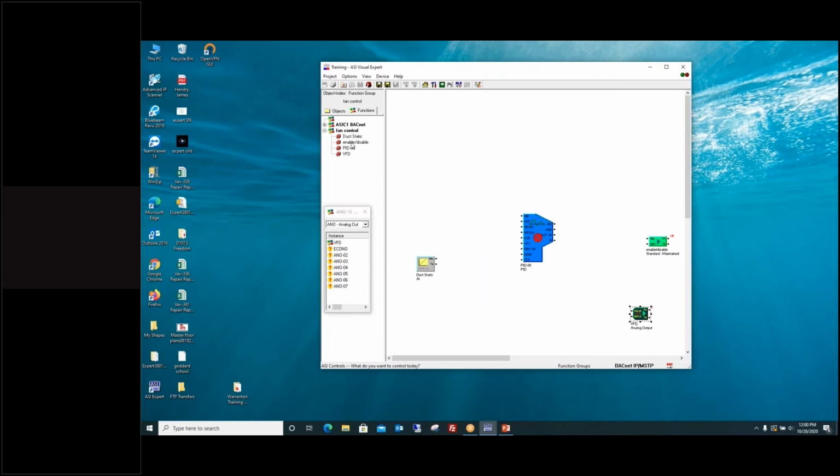Okay, then you're missing a binary value. So hit your drop-down menu for the objects box and find BV for binary values. It's in alphabetical order. Go up to the B's, binary value. Drag one of those below duct static. Just down below would be a little bit better.